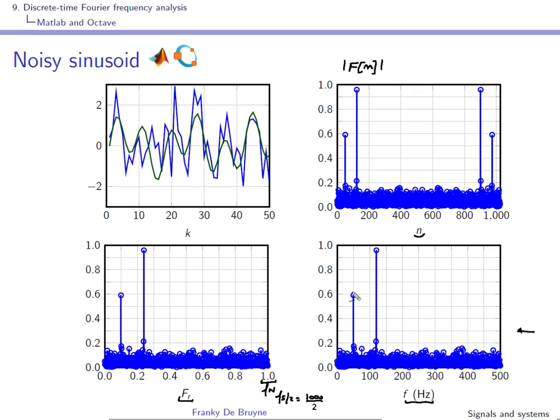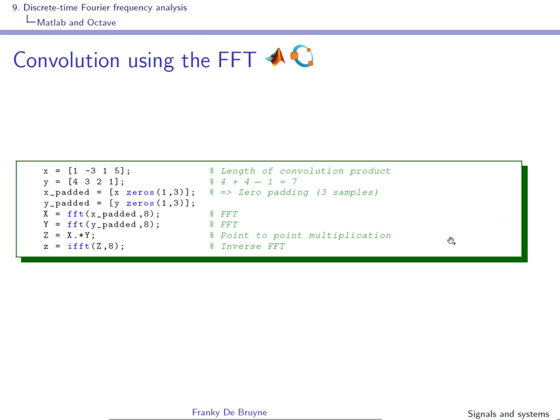1024 data. Here again the amplitude is 0.7, but again, because of this noise and this finite amount of data, you don't get the amplitude 100% correct, but at least here you see clearly the presence of these two sines at the frequency 50 and 120 Hz.